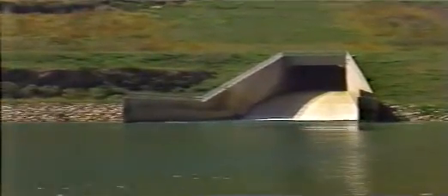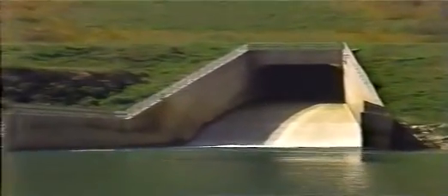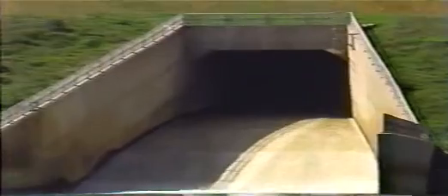Cavitation may appear as pitting at first, but then becomes deeper and more extensive with time. Erosion is the wearing away of a flow surface caused by rock or soil particles suspended in the flow, being swept over the surface at a high velocity. Like cavitation, erosion damage is progressive and can be very destructive.